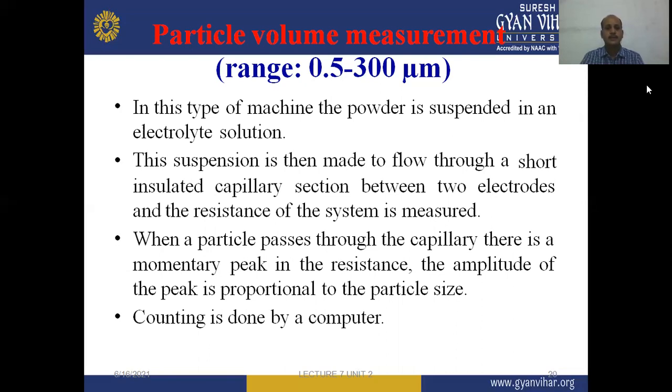Now, in this type of machine, the powder is suspended in an electrolyte solution. The suspension is then made to flow through a short insulated capillary section between two electrodes, and the resistance of the system is measured. So this is the principle of this particle volume measurement method.